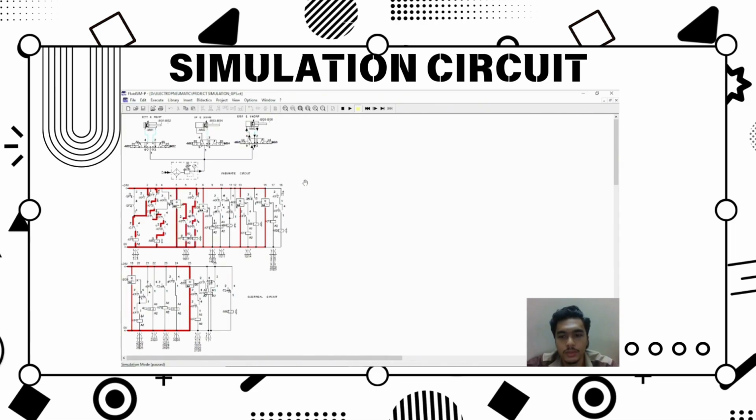Then magneto proximity sensor -BG4 will activate and energize the coil relay -KF2, that through relay -KF7. Then relay contact -KF2 will close and flow the current through relay contacts -KF5, -KF7, -KF6 in normal close contact to activate solenoid coil -MB5. Then activate left switching position and allow air to flow from port 1 to port 4.